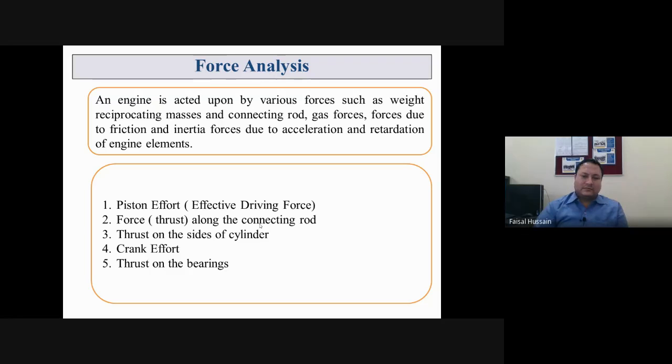For example, we have to analyze different parameters, such as what will be the effective driving force, that is your piston effort, what will be the force produced along the connecting rod, the thrust on the sides of the cylinder, what will be the crank effort, and what will be the thrust on the bearings. If all these 5 points are considered, then it comes under the category of force analysis.